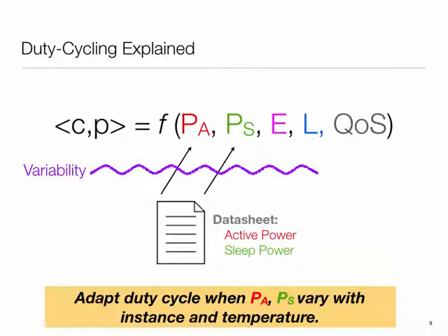So adapting duty cycle turns out to be a strategy which gets used. There are other places where, for example, I refer to battery, but instead of a battery I may have a harvesting system, and then depending upon how much energy I happen to harvest in that location, I can adapt the duty cycle frequency to match that, so that I get a sensor operating at maximum performance. So duty cycle can therefore be adapted.